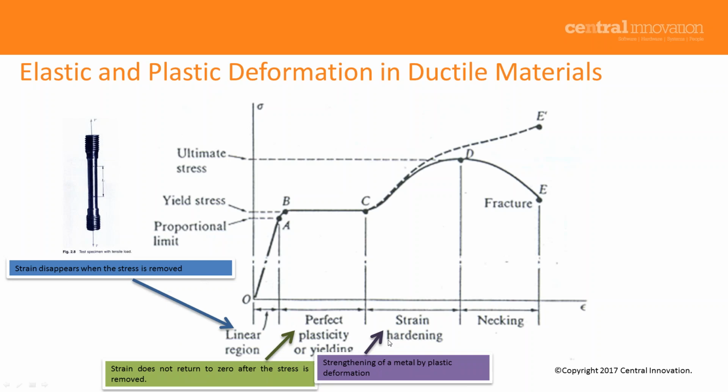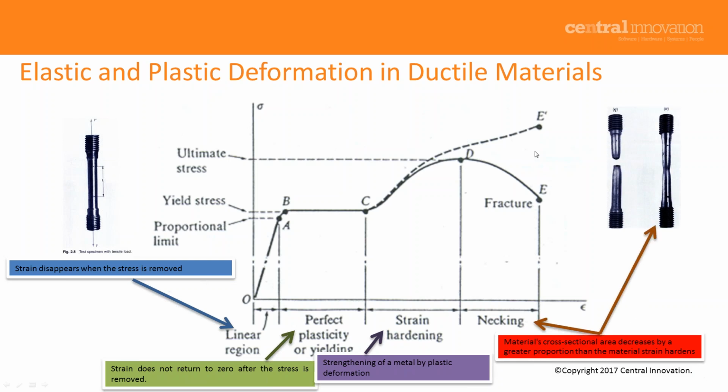The plastic deformation will occur and the material will develop some hardening on its surface. It will resist more deformation until it reaches our ultimate stress point, and from that point we will see the necking problem and finally come to fracture. So this is the behavior of any ductile material. As I said, a very good example is steel products. So we have to understand all this procedure.